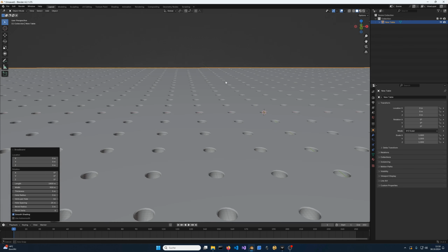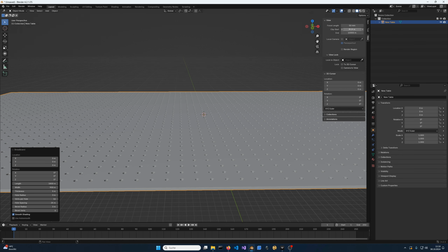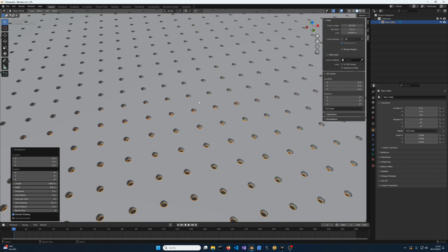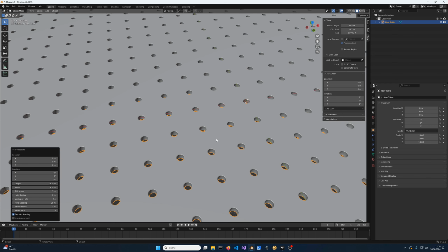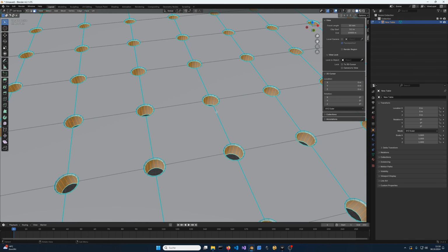And then, as I said, unchanged from the previous version of this add-on, there is the option to create an optical breadboard, by default rather large. So let me change the view settings. So this is a tabletop with a lot of 6mm holes, because they normally have an M6 thread, these optical tables. And of course the thread is not modeled, because that would create way too many vertices. You can instead, if you want to, generate them by shader. And to simplify setup of that, by default, if you go into edit mode, all the faces inside the holes are pre-selected, so you can easily apply a predefined material to these faces in particular.